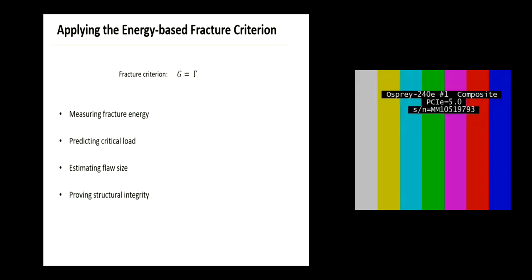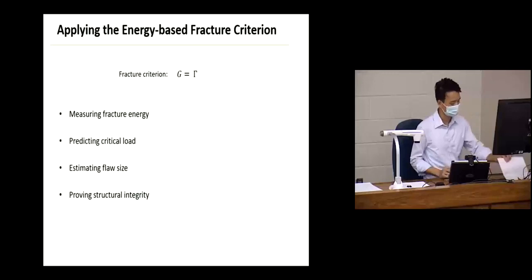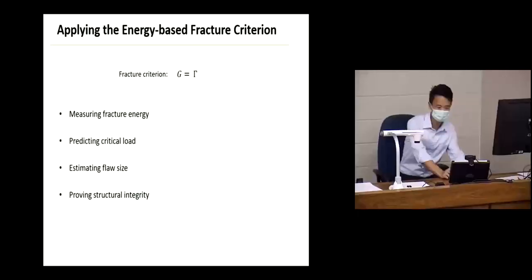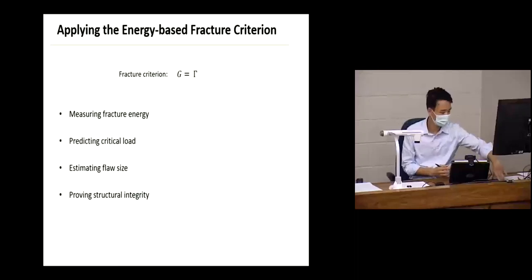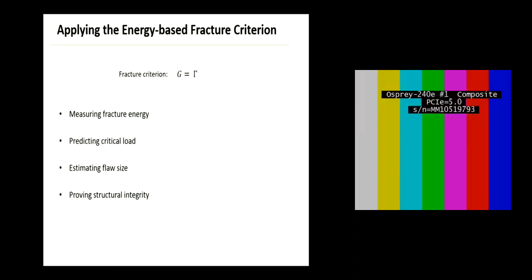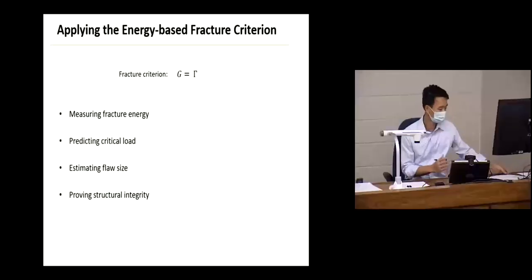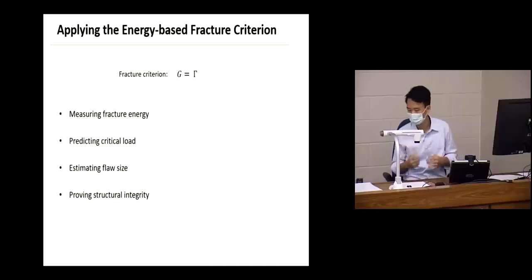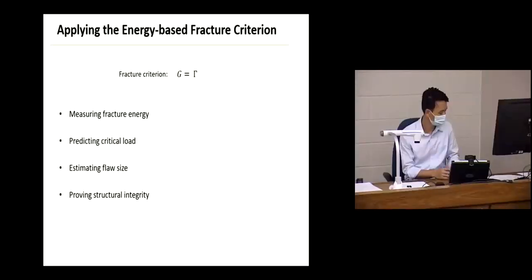Sometimes you get a piece of steel that can be ductile, but at low temperature it becomes brittle, and vice versa for ceramics: you heat it up, it becomes more ductile, and the fracture energy goes up. So these things are not constant, right? They depend on many factors, experimental conditions and microstructures.